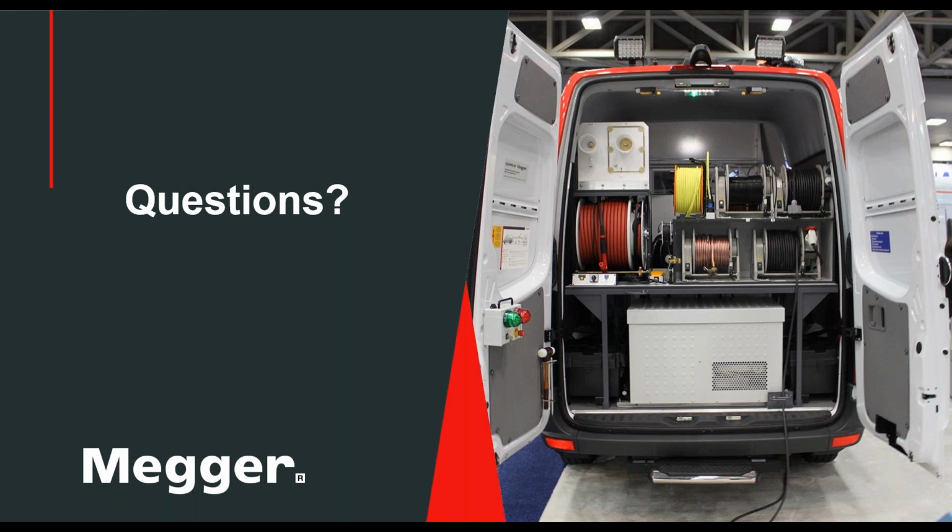Yeah, maybe I can add a little bit to it. If you have extensive branching, like in downtown city networks, then typically the TDR method or arc reflection method is not going to be very successful, because you get a lot of attenuation of the radar signal, and the other thing is, even when you get a signal, you have to be able to associate that with a certain point in the circuit.